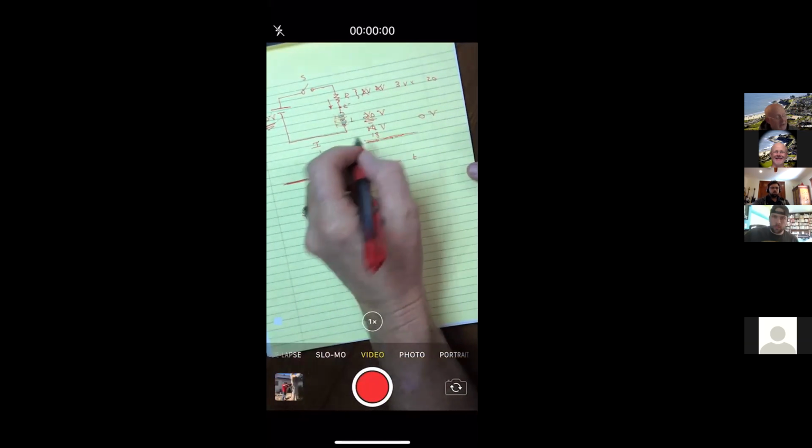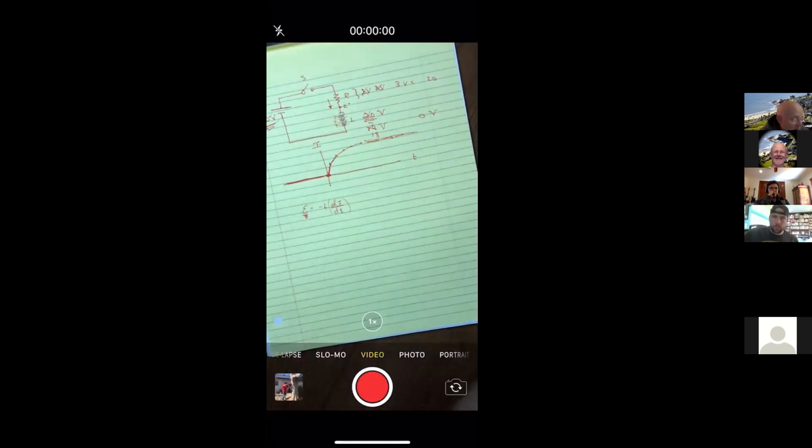And so it's a constant, and then it just remains that way. That's why you can treat it like a wire, because there's no resistance coming from it. So that's why we would say after a long period of time, you could just treat the inductor as a wire. Awesome. Thank you so much.